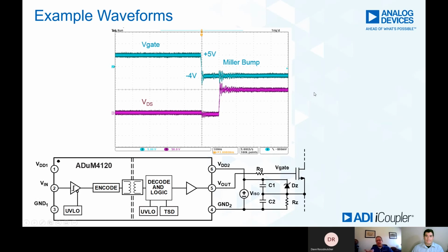Okay. And with that isolated supply that you choose, it just has to be able to supply the Zener regulator current as well as the maximum gate drive current required to turn the device off and on. Exactly. And the isolated power supply that you choose for this example would be 9 volts because we're spanning the whole +5 and -4 volts in this system. Okay, very good.